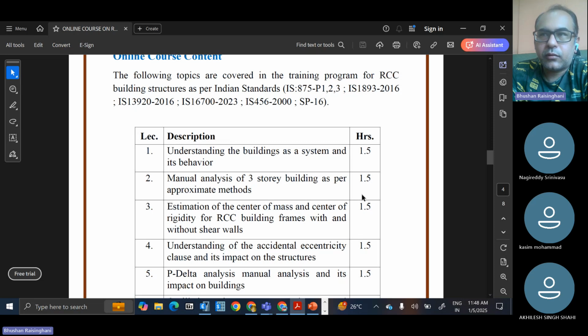Two-side distribution, what will happen? It is mostly based on the stress and strain analysis. Whenever the load is applied on a column in one particular direction, like MU1 and PU, force is applied in one direction. So there are two phases, one phase in compression, the other phase in tension. Each reinforcement, as a layer, will have the strain developed in it. Based on that stress-strain analysis, you will come to know whether two-phase reinforcement is able to satisfy the results or not.